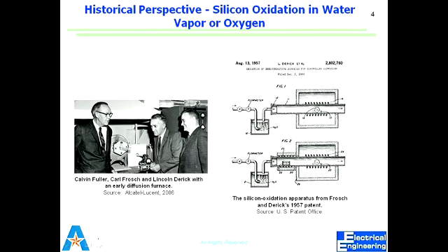So silicon nitride again serves the same purpose. It's an insulator, which means it's electrically different, and it can have a passivation effect, which means it covers everything that's below and doesn't let further reactions happen.